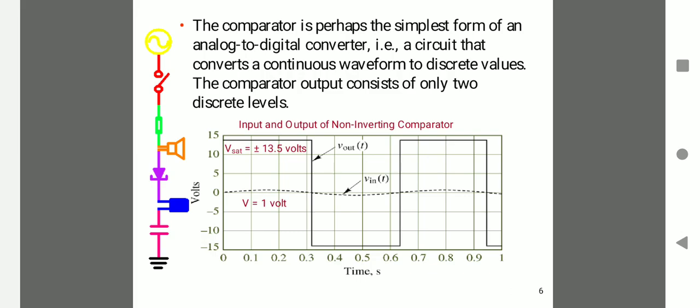The Schmitt trigger is also called a regenerative comparator, as it is designed with positive feedback, which produces a regenerative action that makes the output switch levels. While using positive voltage feedback instead of negative feedback, the feedback voltage aids the input voltage instead of opposing it.